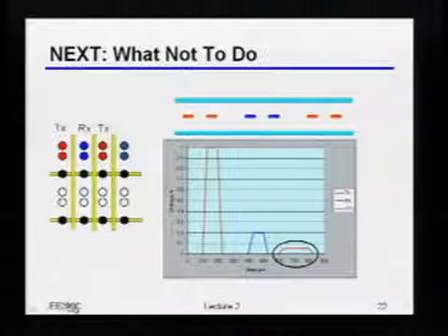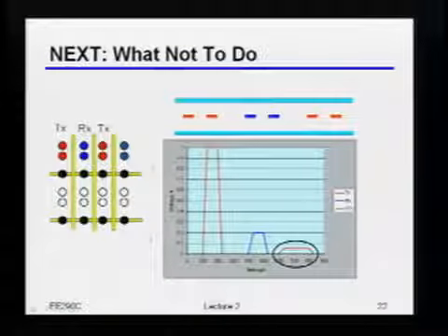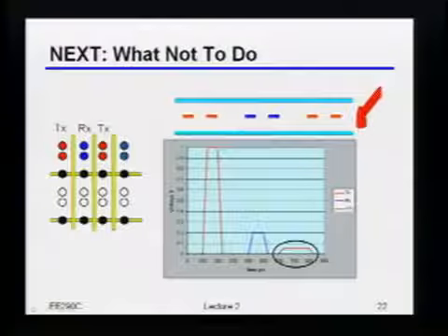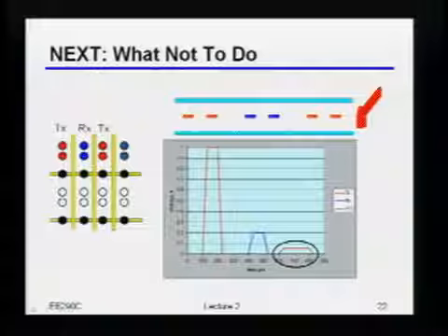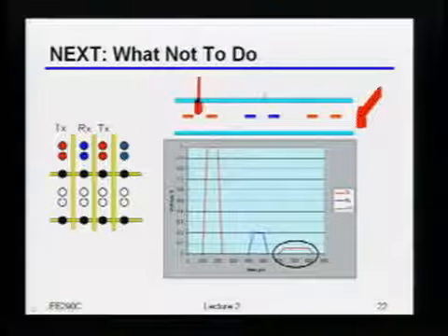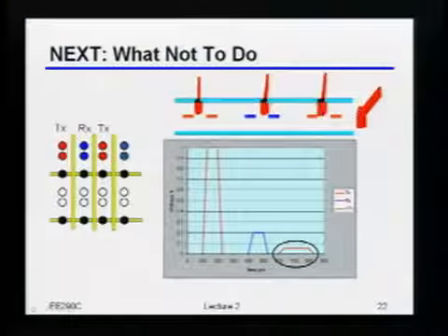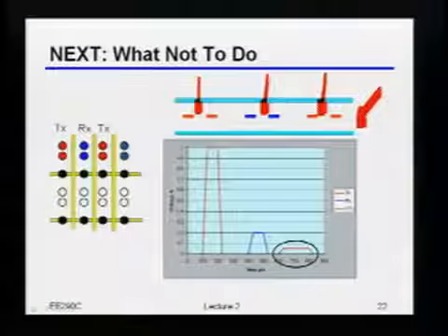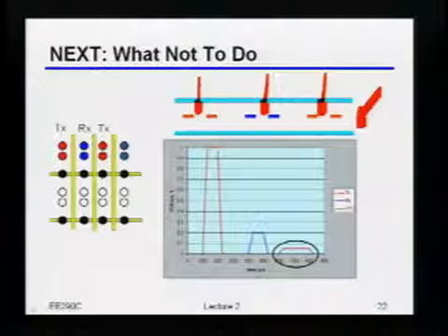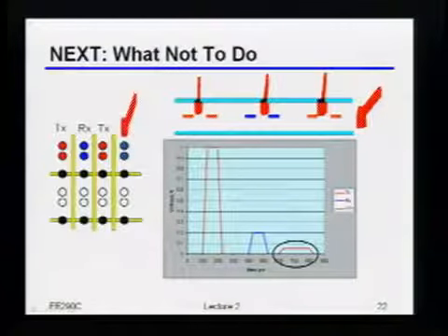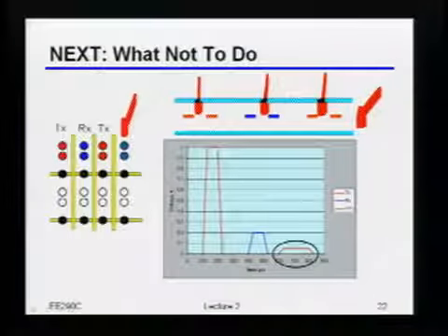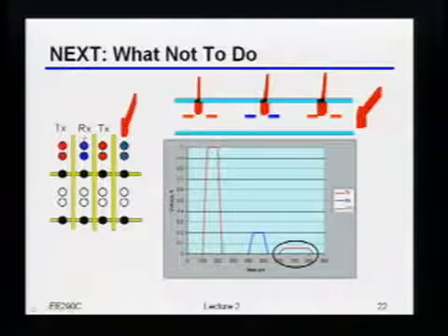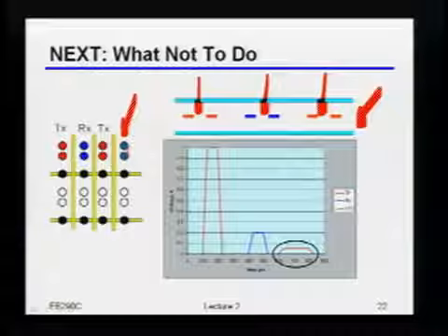I'm showing you two different scenarios here, but they both translate into the same thing. Here I'm showing an example of how I might arrange the backplane. I might arrange the backplane so that I've got a transmitter, then a receiver, then a transmitter, then a receiver, and so on. I'm just alternating between them. Similarly, if I looked at the connector, looking at the top view going down, I could also arrange it with a transmitter, a receiver, a transmitter, then a receiver, and so on.